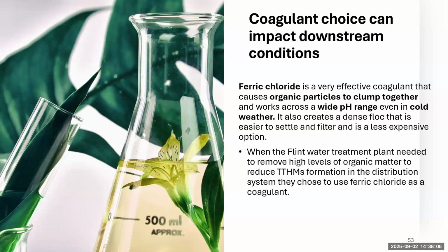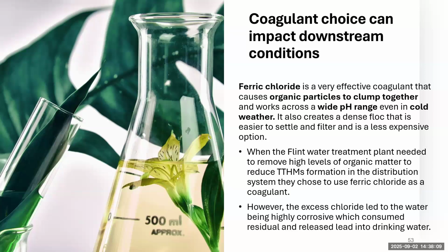Seems like a win-win. However, the excess chloride in that coagulant increased the chloride levels in the water and led to the water being highly corrosive. And it not only resulted in the lead problem, but it also used up the chlorine residuals and caused problems where some people actually died from not having properly disinfected water.